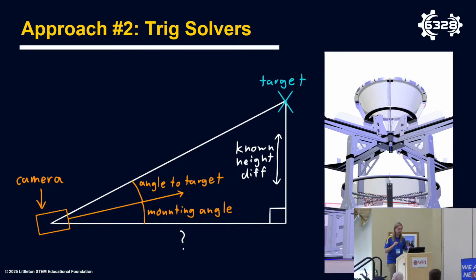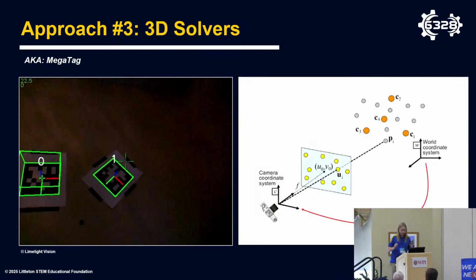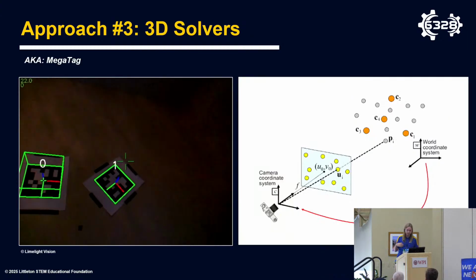This also relies on having a very accurate gyro position. That can be a major disadvantage at times, since even the best gyros can and do drift. If you want to see a demonstration of that, try running an FRC robot into a wall at full speed and see how your gyro likes that. The results will not be pretty. Okay, so trig solvers still have those couple of problems.